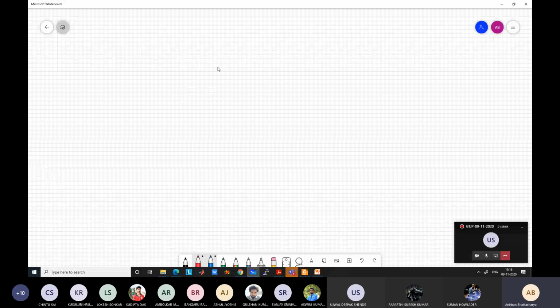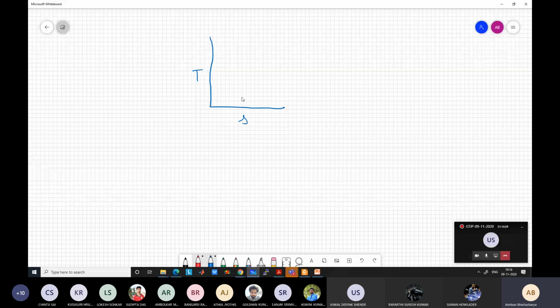So how will this TS diagram look for an isentropic nozzle? This is not there in the notes because we will be considering actual cases, but let me just show you. This is the nozzle inlet pressure, I am going to call it P04, and this is the nozzle exit pressure line, I am going to call it P5. This is a choked condition, so ambient pressure is somewhere around here, PA.